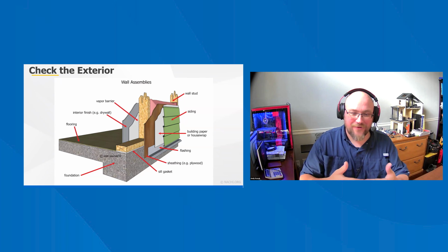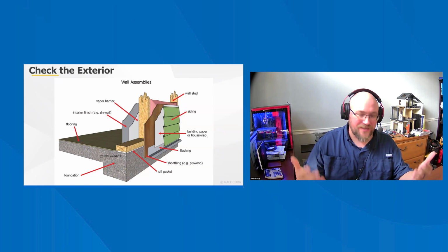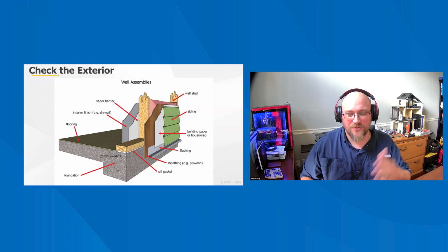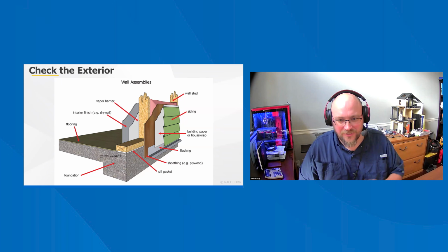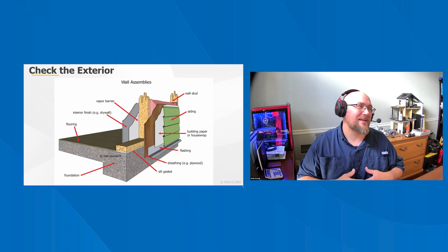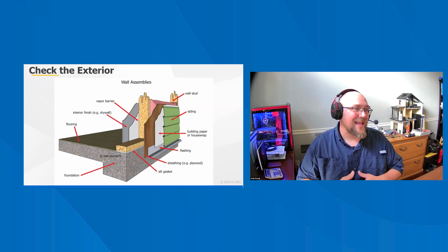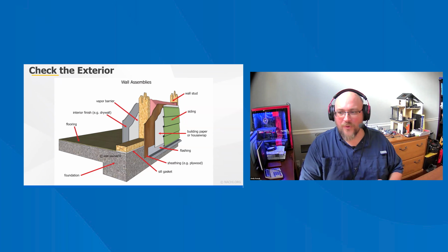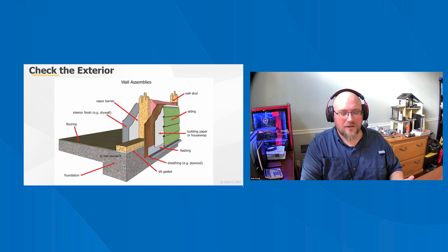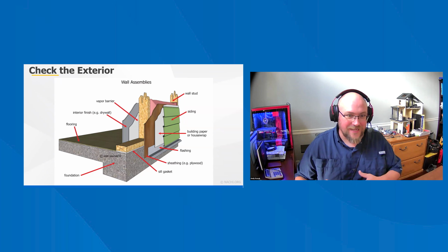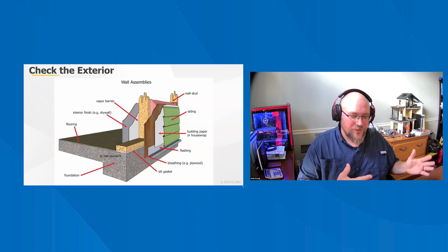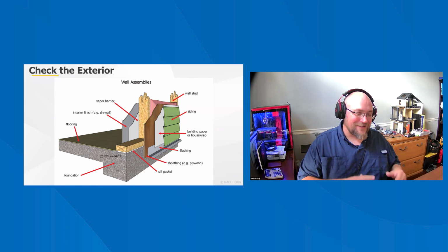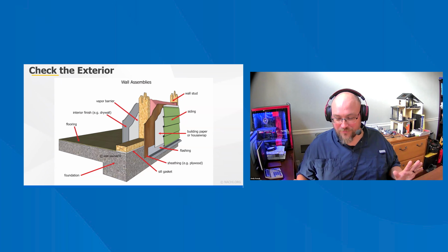It's going down. It's getting to that really poorly installed flashing tape around your penetrations, your windows, your doors, and then it's getting into the interior of the walls. And so there's a picture at the end of this of a multi-million-dollar house where there were, I don't know, 50 or 60 windows, and over half of the windows leaked every time it rained. And so they basically took the siding off and reflashed, and over time, because we made them do it 3 or 4 times. It wasn't up to me to just prescribe the repair.